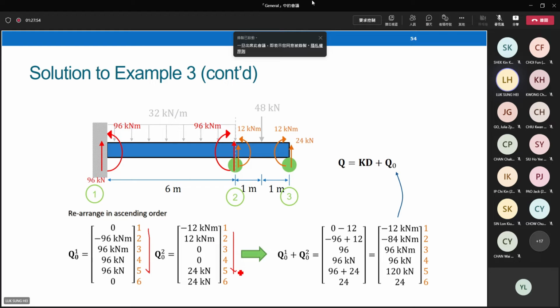Fill 0 for those missing elements. Say for example, element 1 involves code numbers 2, 3, 4, 5. No code numbers 1, 6. You can fill them with 0 so that the vector is equal to a 6x1 vector. It makes it easier for you to observe which parts should be combined with each other.